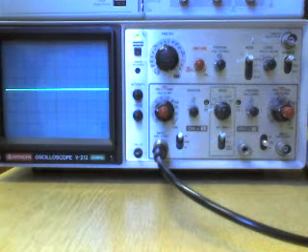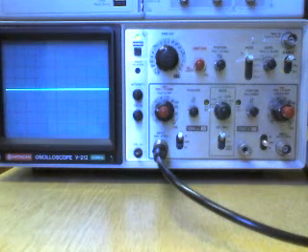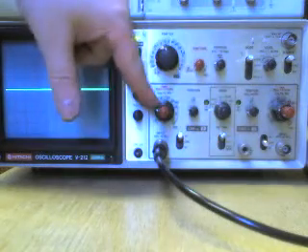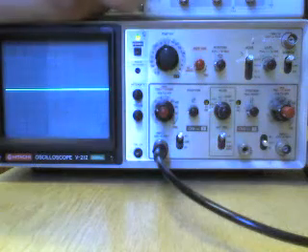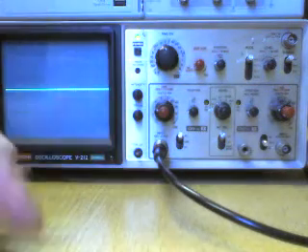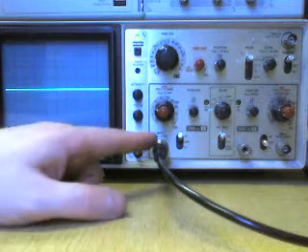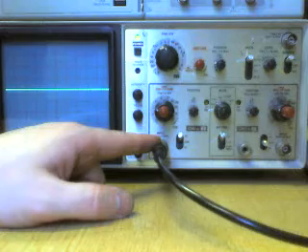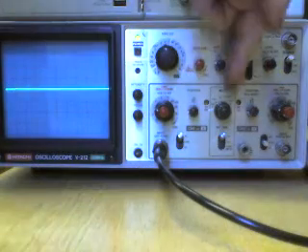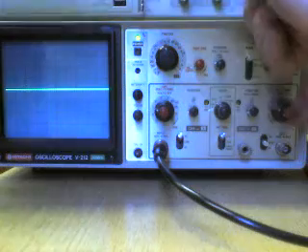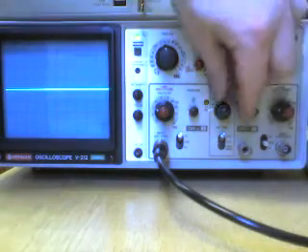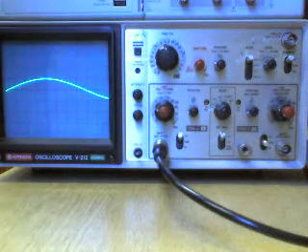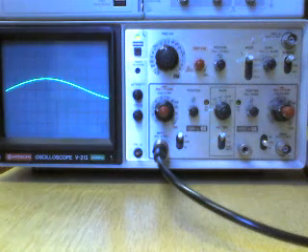Well, what could be the problem? Let's go through the controls. Let's see. Right, well, our time didn't do anything. Our voltage per division didn't do it. Have we actually got our oscilloscope viewing channel 1? Like I said, we can view 2 channels at the same time or independently. Our mode is currently set to channel 2, so we're actually currently looking at this one over here. We switch it to channel 1. There we have our sine wave, or part of our sine wave.